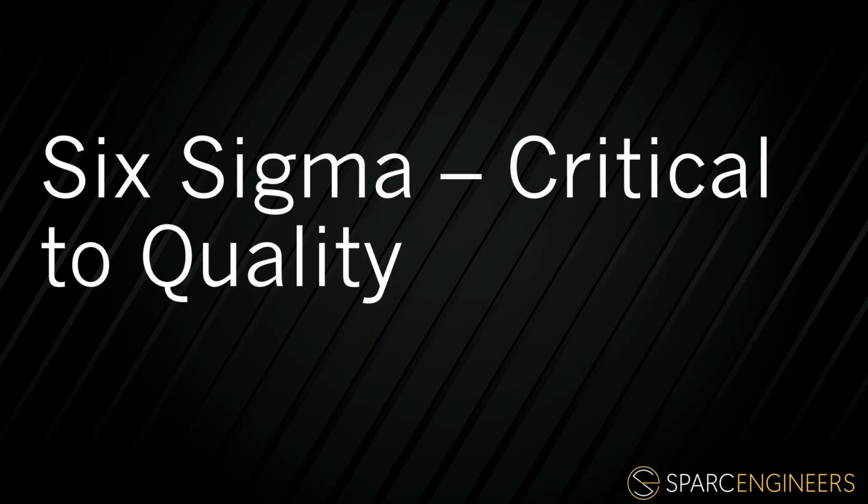In the define phase, we talked about voice of the customer. VOC helps us understand what the customer wants, needs, or expects. CTQs take that customer language and translate it into measurable requirements. This is important because we cannot improve quality in a meaningful way unless we know what quality means from the customer's perspective. In this section, we'll look at what CTQs are, how they appear in manufacturing, how they differ from internal metrics, how they connect to process capability, and how they are used throughout DMAIC.